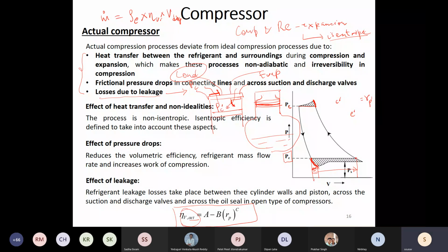If you provide a very thin plate which can open at extremely small delta P, then it will require less overpressure. That's what I was saying. So the valve will open at a certain other pressure higher than your expected PC. So this is your PC prime, and this is where you will start discharging.